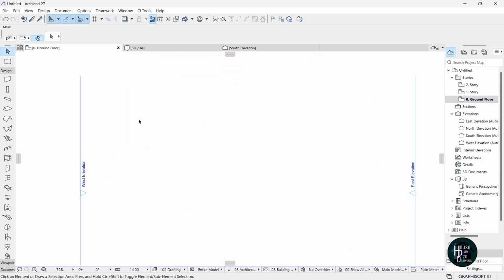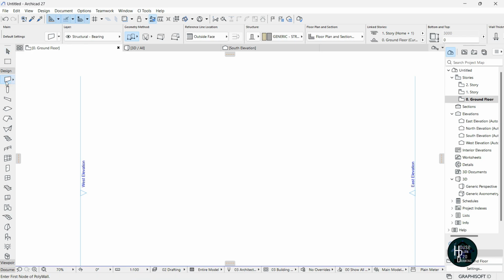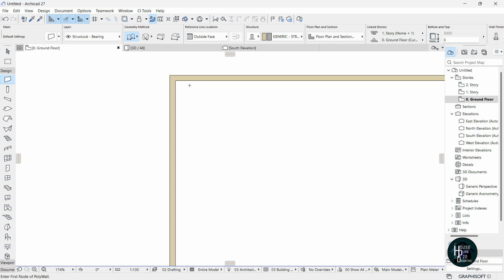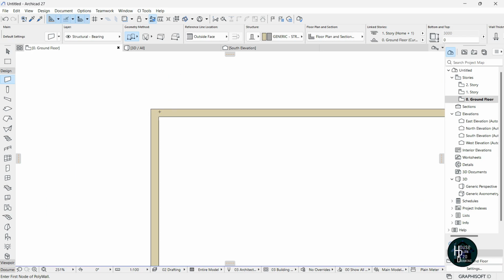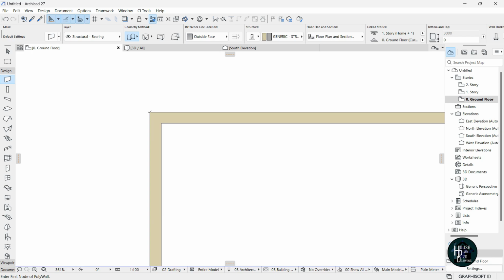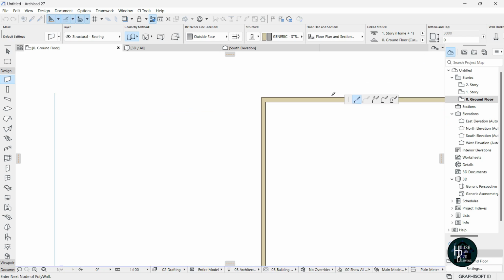The next thing I want to do is click on the wall tool. Once you click on the wall tool, I want you to click, drag up, click, and drag up and drag like this, then double click. Once you do that, you're going to have something like this, a wall here and another wall here. Next, put the cursor at the top edge here, allow it to load up. Now let's give a distance of 5. Click enter and stretch it down.